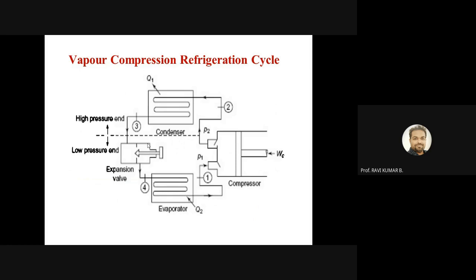So in order to reduce the cost to the optimum level, we use the throttle valve or expansion valve. A throttling process is one where the gas or liquid coming in suddenly expands over a short length. There will be a significant change in pressure, but very little change in temperature. You can treat the enthalpy as constant while pressure reduces significantly. For that purpose, we use the expansion valve here, along with the compressor, condenser and finally the evaporator.